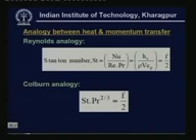So Colburn has improved this for different Prandtl numbers, and he has arrived at what is known as Colburn analogy. This is given by Stanton number into Prandtl number to the power of 2 by 3 is equal to f by 2. This is known as Colburn analogy. This is applicable to a Prandtl number varying from about 0.6 to 50. So you can see the usefulness of this.